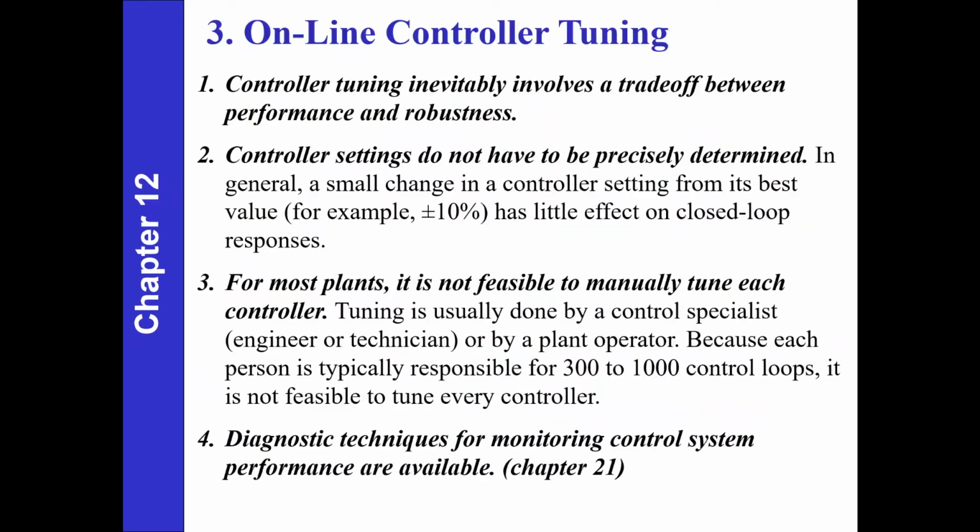So by that, I really hope that you can understand what is the application of controller tuning, why we really need to do this tuning. Because Kc, tau I, and tau D have their effect on the response, and we want a good response. What are the characteristics of a good response? Short settling time, less overshoot, short rise time, right? And whatnot.